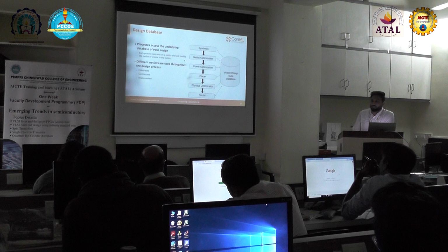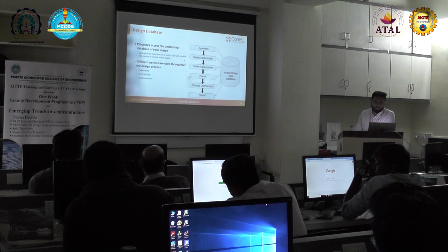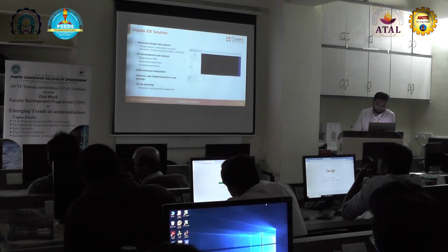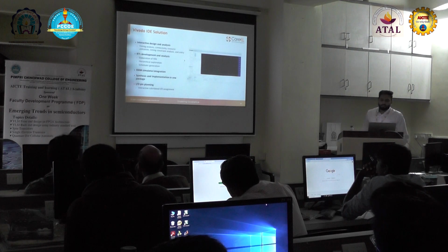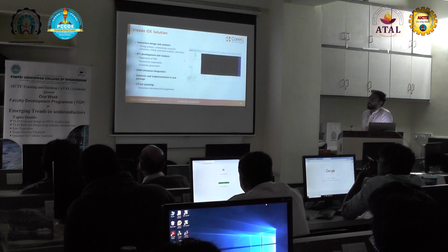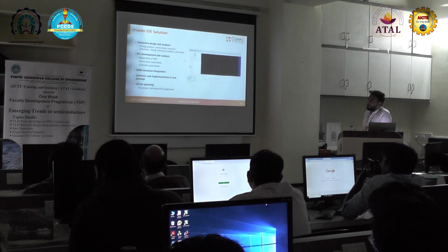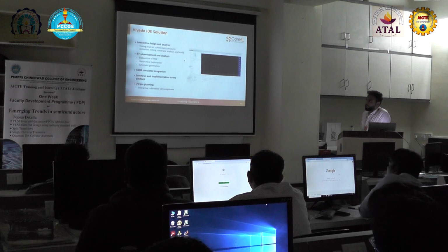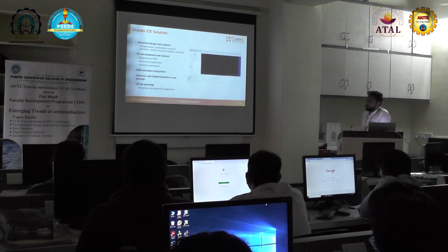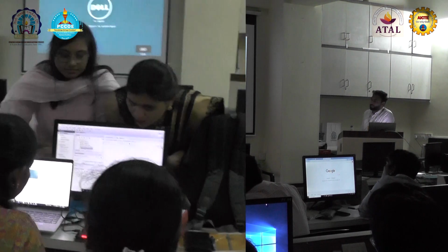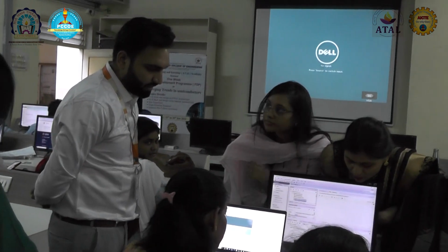So all these databases are included in the Vivado design. In the Vivado IDE solution, we have interactive design and analysis, RTL development and analysis, XSIM simulator integration, synthesis and implementation in one package, and IO planning, all available from the start.